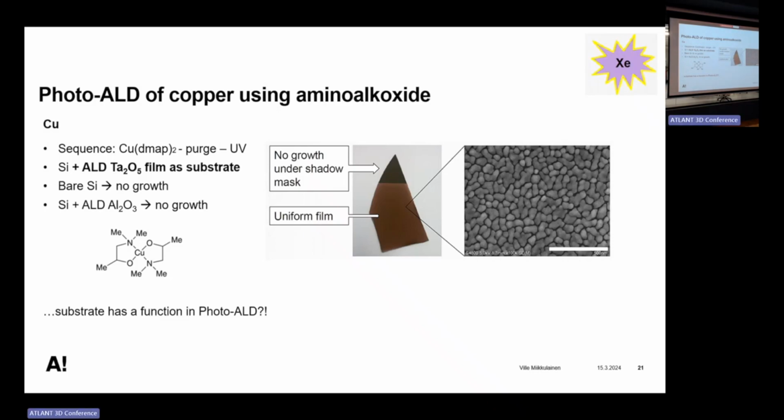I have two questions or remarks. The obvious question is, would it not be very interesting to use an excimer laser or a quadrupled YAG, because then you have only UV? And an additional feature that the laser can give you is that you could put most of your substrate below the ALD window, and you locally heat it with your laser, so that where your laser is, you are in the ALD window, and the rest stays cool.